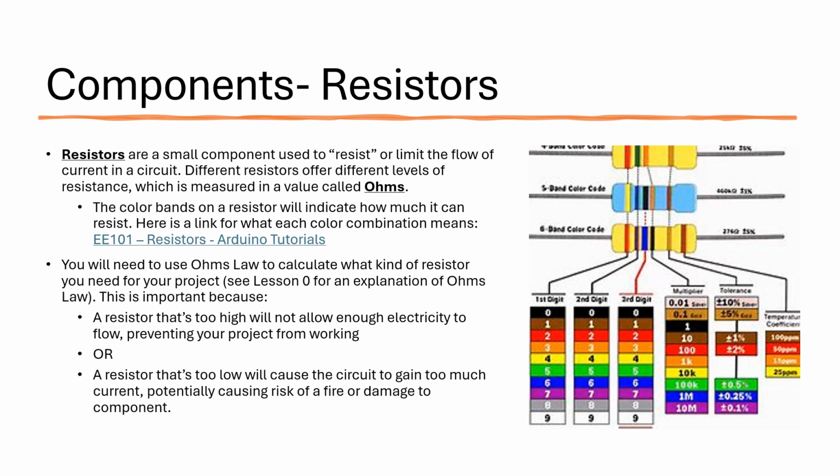However, there are various resistors with varying resistance. Using a resistor that's too high will prevent the project from getting the power it needs. Using a resistor that's too low could cause too much current to flow, potentially breaking your components. To know which resistor to use, you need to know Ohm's law.